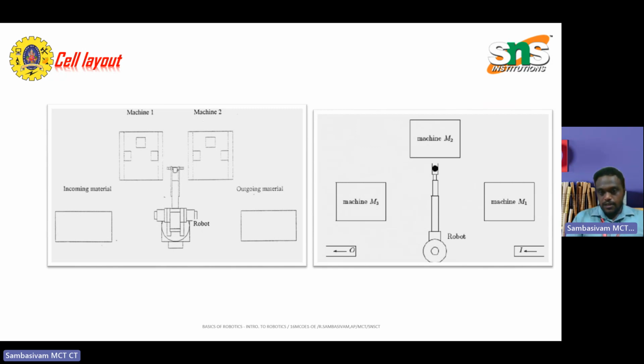Once that is done in the second spot, the part is taken to a second machining part, where all the surface finishes, outgoing process materials, quality finish and surface finish are covered. Then the robot goes to the machining center, takes the workpiece and delivers it to an outgoing conveyor, where the end product is delivered to the outgoing space.